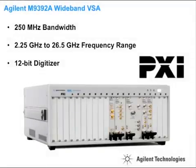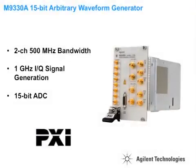Performing digital predistortion measurements requires 2 to 5 times oversampling to accurately model the power amplifier's higher order nonlinearities. To support this, the M9392A vector signal analyzer with 250 MHz instantaneous bandwidth and the M9330A arbitrary waveform generator with up to 1 GHz modulation bandwidth can be used to support many emerging wireless communication standards.